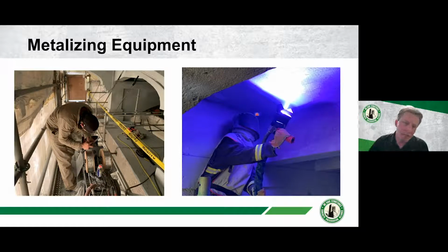Because of the zinc dust, this installer here is wearing a hood with supplied air. So it's kind of a significant process here. And then what happens is, as this installer's applying the zinc, the installer is continually moving left and right and up and down and developing a spray pattern. Each pass, you get about 3 to 4 mils of zinc installed onto the surface of the concrete, with a target of typically between 12 and 18 mils on concrete.